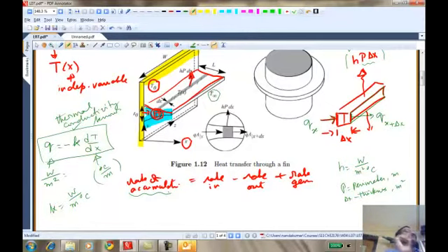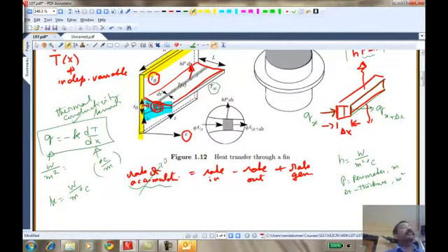So we're going to make a simplifying assumption that there is no accumulation, meaning it is operating under steady state, so that we can answer questions once this fin reaches a steady state. But we cannot answer any questions about how long it takes to reach that steady state. That's an assumption. Later on we will relax that assumption and see how to develop a model when you have transient effects as well. And that is also in chapter 1 of the book.